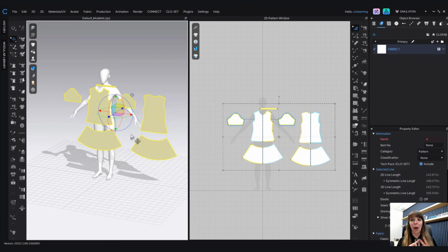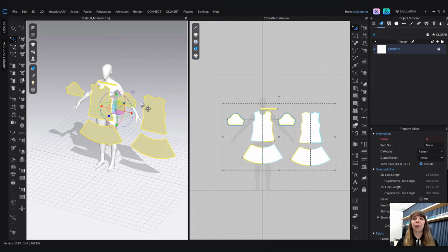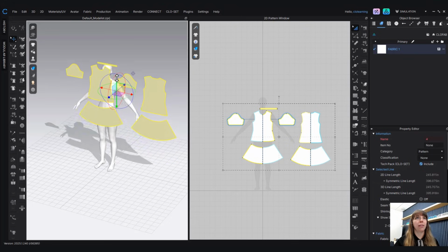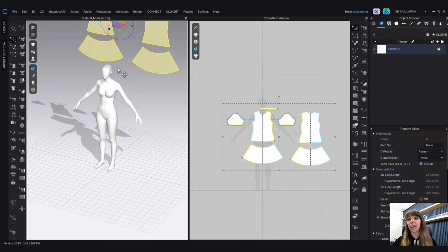So that is our X, Y, and Z axis. X is our horizontal axis, Y is our vertical axis, and Z is our forwards and backwards. What I like to do when it comes to looking at these gizmos is look at it from a 45-degree bird's eye angle. And that's because it's going to give me a very clear visual path, and none of those circles are blocking any of the arrows then. I'm going to take the green arrow, and as I highlight over it, bring that up and out of the way. Again, just clicking with my left click and dragging.